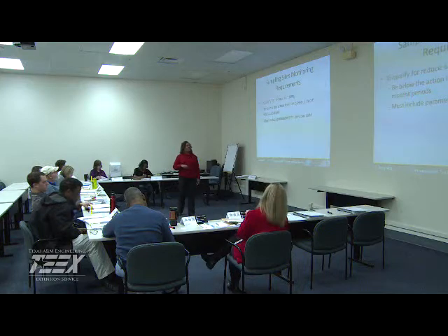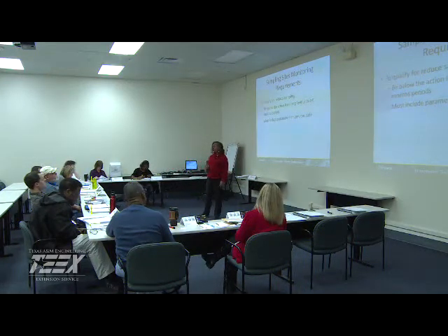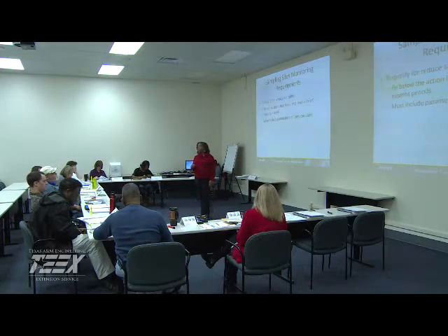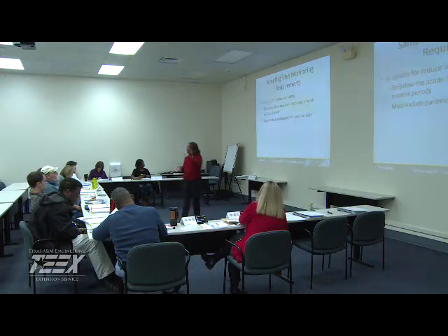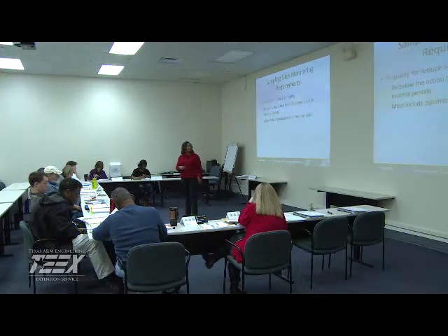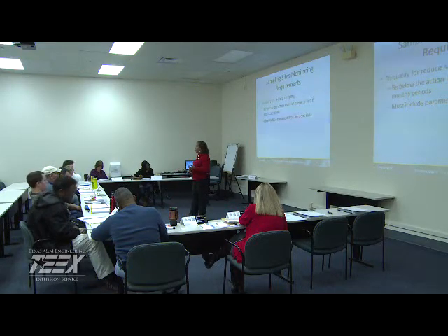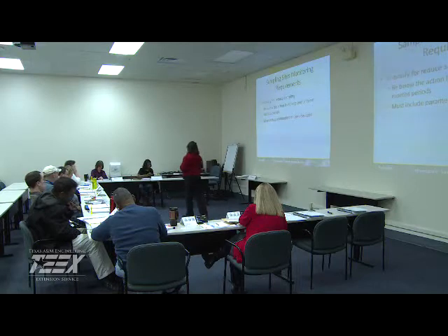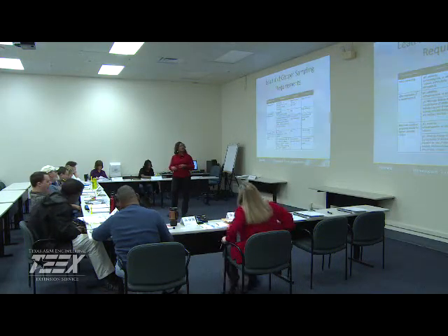Now, to qualify for reduced monitoring, Lori was pointing this out, you have to be below the action level for the previous two six-month periods. So you have to demonstrate this is the norm. This is my baseline. I don't have a hit consecutively. And you must include those water quality parameters: the pH, the conductivity, the orthophosphate, the silica, the temperature. All of those must be part of it also.